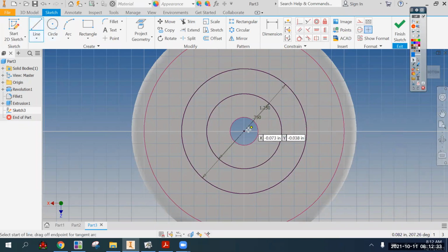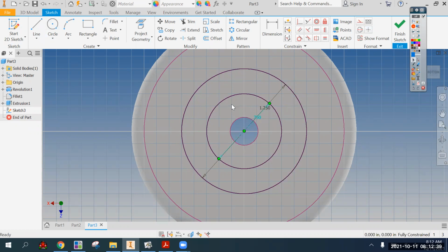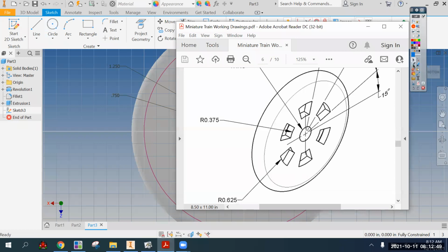Then the shape is just a line that goes, and I'm going to get these dimensions out of the way because they're going to look like actual lines. So we just need lines that connect the inside arc to the outside arc in one of these locations, and then close it off and cut extrude the whole thing.